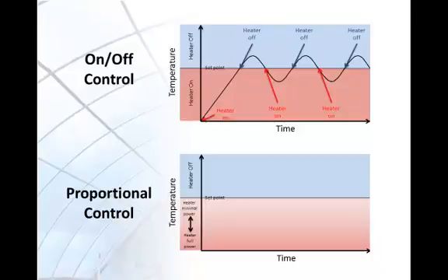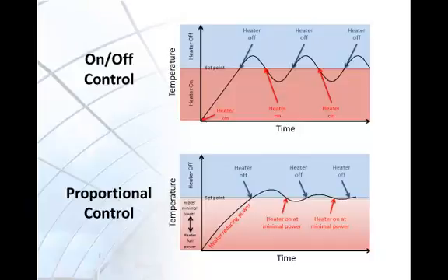So let's turn the heater on when the greenhouse is cold. The heater starts at full power but reduces closer to set point. Therefore, the overshoot is not so bad. On again at minimal power, small overshoot, and so on until the oscillation nearly disappears. It is important to note that with certain controllers, there are ways to make corrective equipment that is simply on or off work to do proportional control.